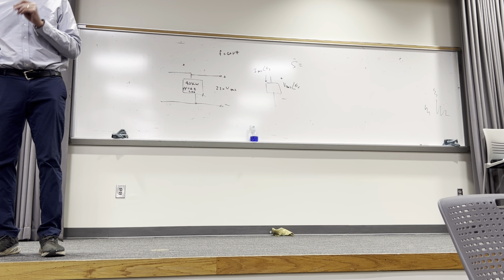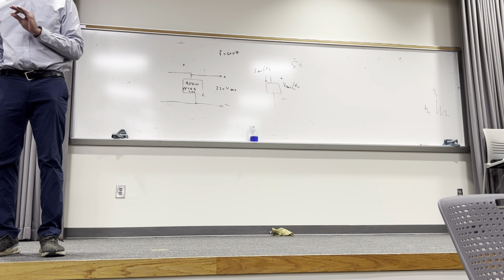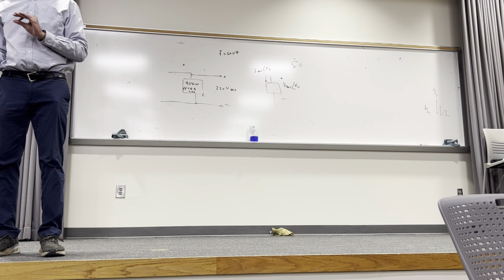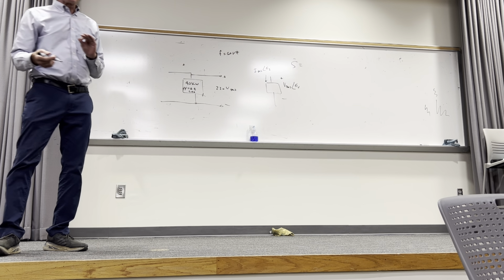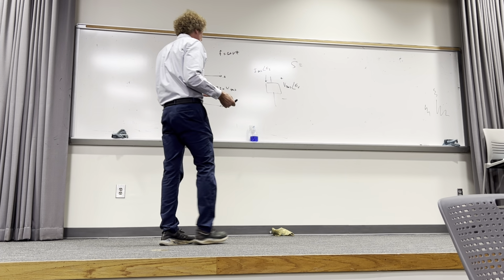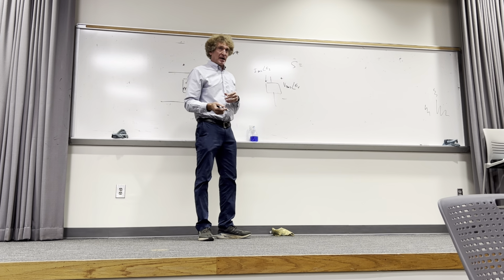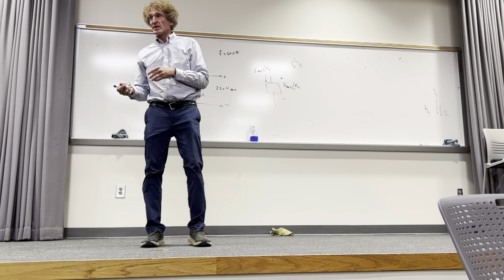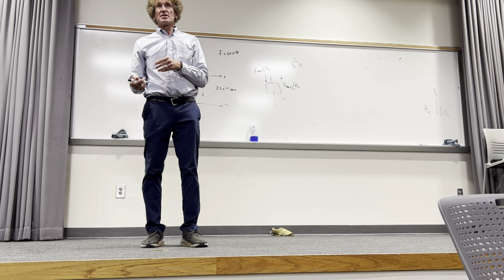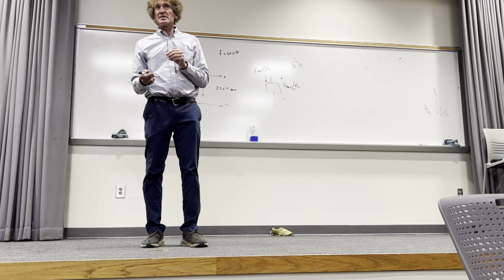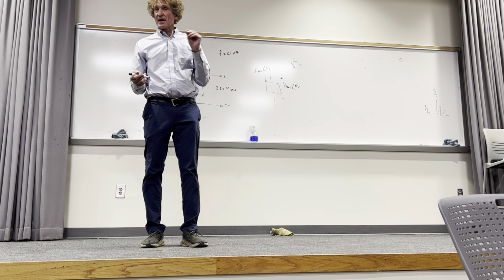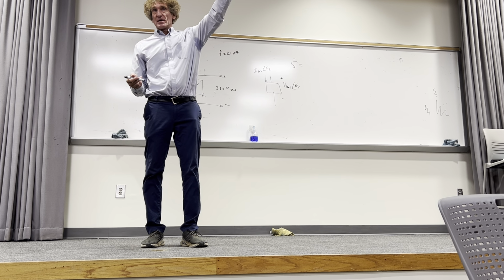Do you all follow me on this? I'm just making a point. There'd be a 90-degree difference in current and voltage for a capacitor. If this was an inductor, and we had j omega L as the actual impedance, then the voltage, if it was VRMS at 0 degrees, the current would be IRMS, but it would be at minus 90 degrees. Do y'all follow me? That's that ELI the ICEman thing. Everybody with me? How many understand that, at least in concept?